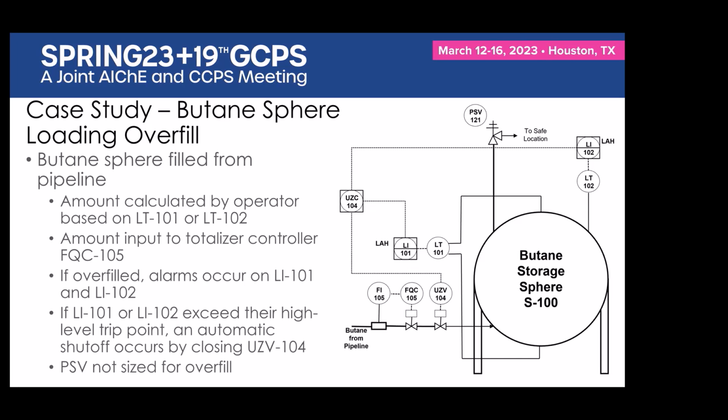So, no, but I was not talking about the BPCS part. I guess in your example, when you're analyzing the alarm and the SIS, that it was a SIL 2, they are not independent. So that was a good example for showing that they're shared components and they were not independent. But by using the fault tree, you can achieve it. Right, exactly. And we were able to do that.